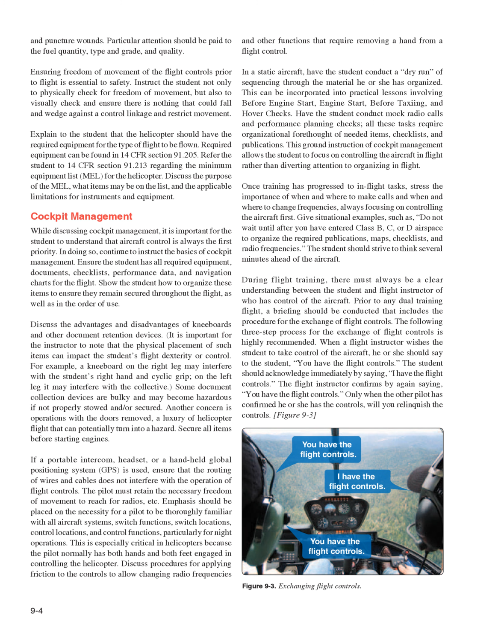In a static aircraft, have the student conduct a dry run of sequencing through the material he or she has organized. This can be incorporated into practical lessons involving before engine start, before taxiing, and hover checks. Have the student conduct mock radio calls and performance planning checks. All these tasks require organizational forethought of needed items, checklists, and publications. This ground instruction of cockpit management allows the student to focus on controlling the aircraft in flight rather than diverting attention to organizing in flight.